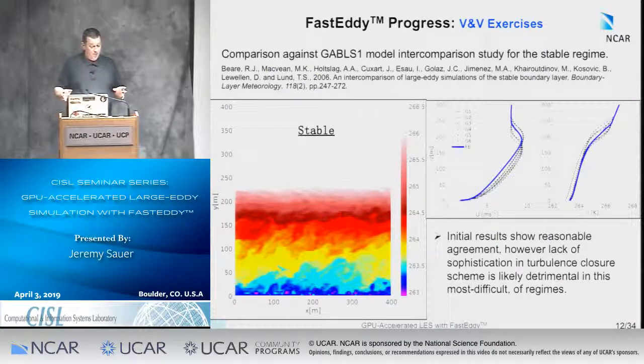So the last stability regime, and really the hard one for LES, is stable. What we used as a basis of comparison for our verification and validation exercises here is a publication from back in 2006 where there was a model intercomparison for Large-Eddy Simulation trying to do the stable regime. One of the reasons the stable regime is so difficult is because the size of eddies that are present in a stable atmosphere are much, much smaller.